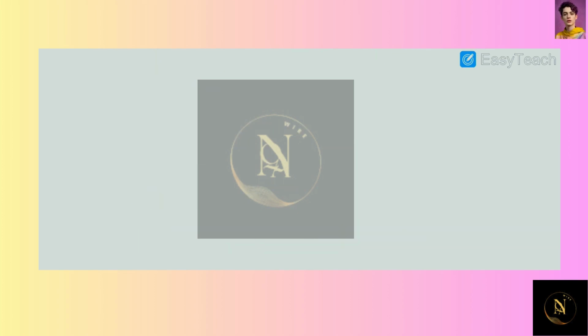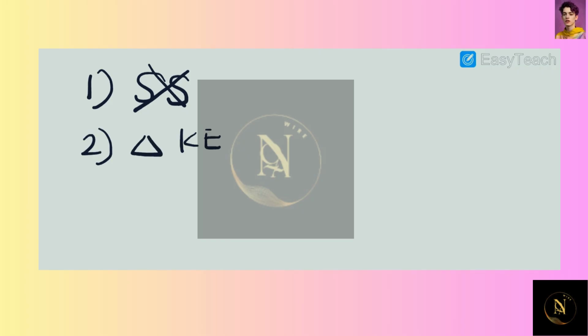So first, what we're going to do is write down our assumptions. We know that this is not a steady state problem because conditions are changing over time, and we can also assume that any changes in kinetic energy, any changes in potential energy, and any work are negligible and are equal to 0.